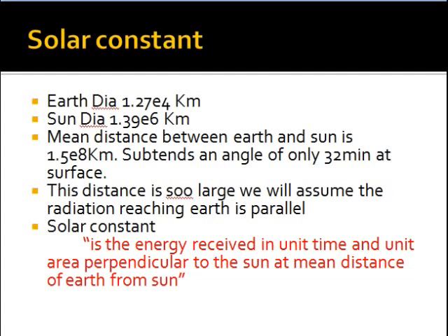solar radiation coming from the sun is nothing but the same as a black body of temperature 5762 degree Kelvin. A black body is emitting the radiation. We clearly assume in that sense. So a black body in the sense which is actually emitting the parallel beam of light, a flat surface of black body which emits the 5762 degree Kelvin of radiation. So this is what we are going to assume for simplicity.